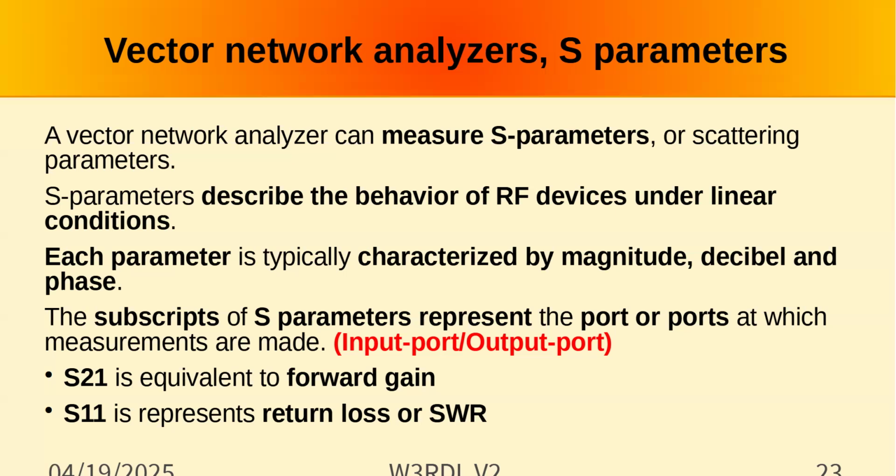So the two main uses are an S11 and an S21. And the 21, you're measuring the response of a circuit by sending a signal through it and seeing how it changes from what you sent. And apparently that's what you cannot do with the Rig Expert. You can't do a 2-1, correct?